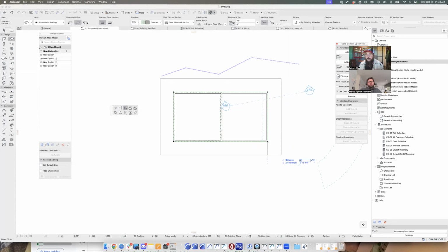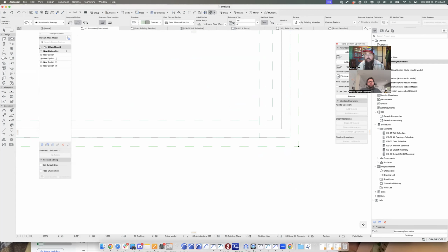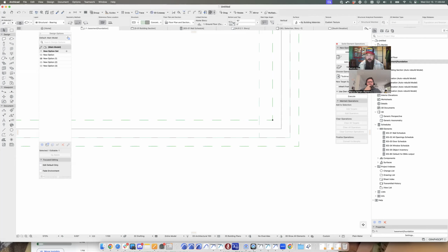And just like we did with that curb, I'm going to do the same thing here, where this is going to be a 2-foot strip footing. So I'm going to offset all edges and hit the option key to offset a copy in 2 feet. And that just gives me something to trace that cropping with. So now if I hit the pet palette again and subtract this out, right? Now I have that area that I can delete, and that was just a tracing piece to know that this footing is 2 feet wide.